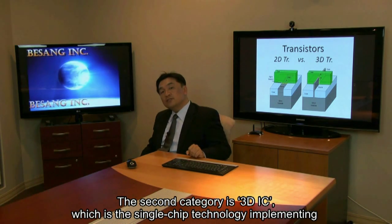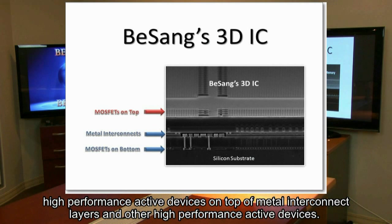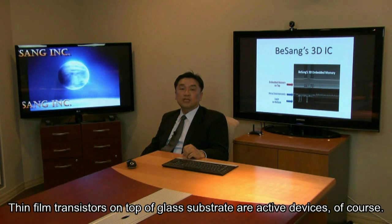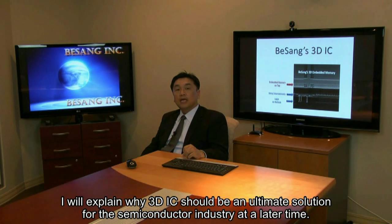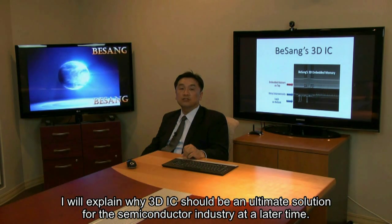The second category is 3D-IC, which is the single-chip technology implementing high-performance active devices on top of metal interconnect layers and other high-performance active devices. 3D stacking of passive devices such as stacked capacitors and poly resistors are not considered as 3D-IC. Thin-film transistors on top of glass substrate are active devices, of course. However, these are not considered as 3D-IC due to low-level device integration and poor device performance. I will explain why 3D-IC should be an ultimate solution for the semiconductor industry at a later time.